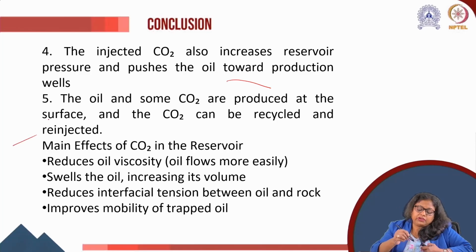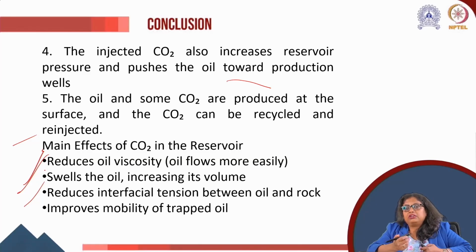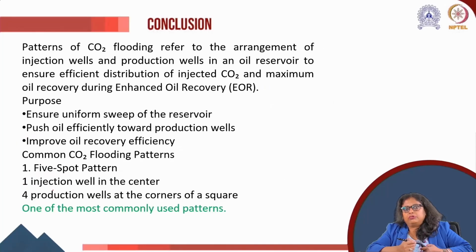The main effects of CO2 in the reservoir are: it reduces the oil viscosity, so oil flows more easily; it swells the oil, increasing its volume; it reduces interfacial tension between oil and rock and improves the mobility of the trapped oil.